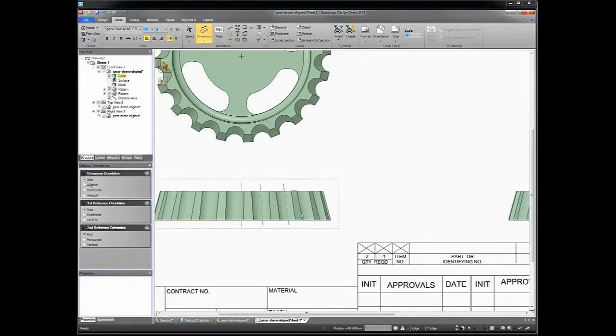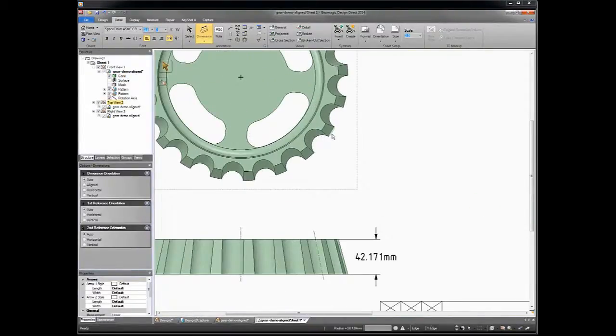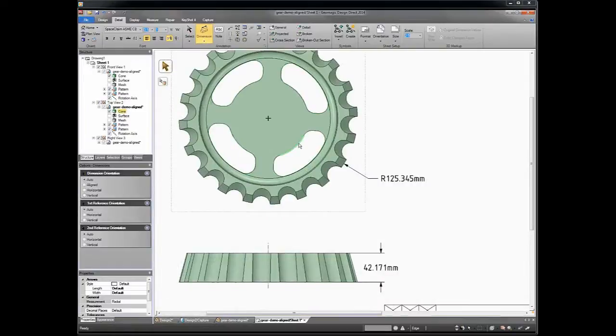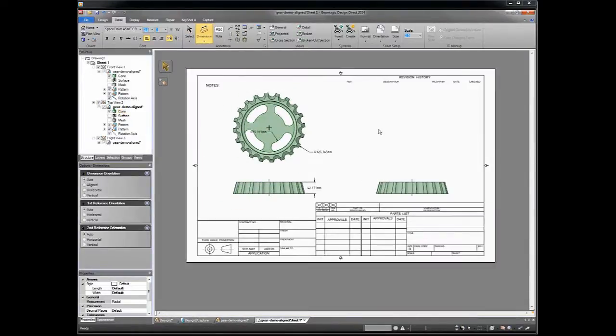I use a nice dimension tool. You just click these lines. If you click one line, it'll dimension that. If you click another one, it does a relative dimension between those two. It's a smart dimension tool, so depending on the entity you pick, whether it's an arc or a line, it'll apply the right radius to it. So you can go around here, dimension your drawing, and put your values on it.